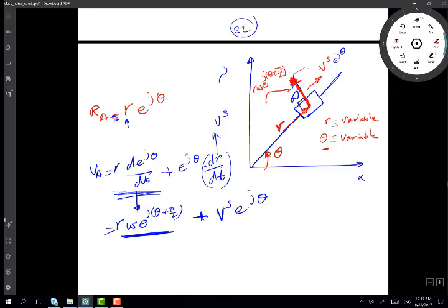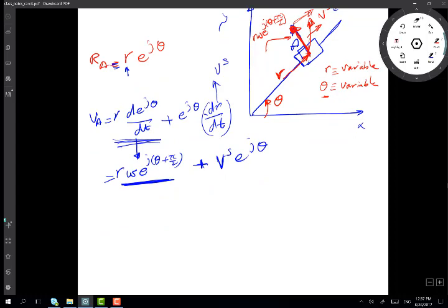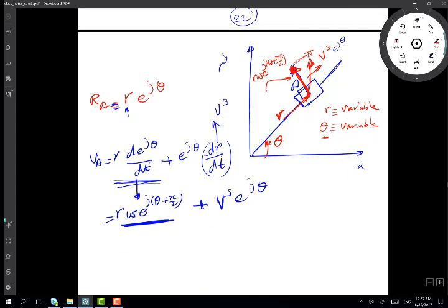So the velocity of the slider will not be perpendicular to the link anymore, but will have both values added together. So that slider will have two contributions: its own sliding velocity Vs, and the contribution it gets from the frame on which the sliding occurs. And this frame rotates and imparts the effect of this rotational motion to the slider as well.